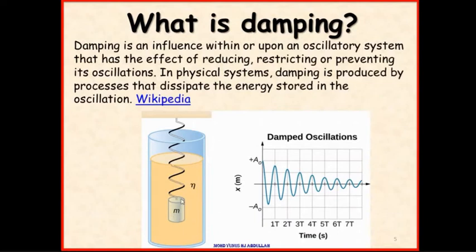So look here, a simple analogy. You have a mass and spring system, then you put it in water, which could be very good for observing. Or you put it in oil, for example. You know that oil has a very thick viscosity compared to water. So the viscosity of the liquid depends on how easily the mass will oscillate. If you put water, it oscillates very well, but with oil it is very difficult to oscillate. So oil and water give very different amplitudes of vibration.